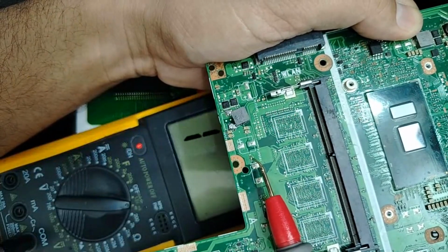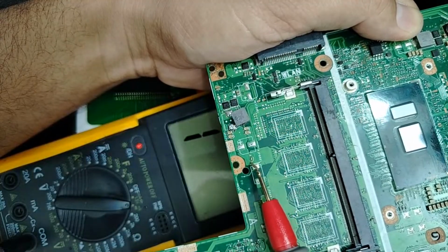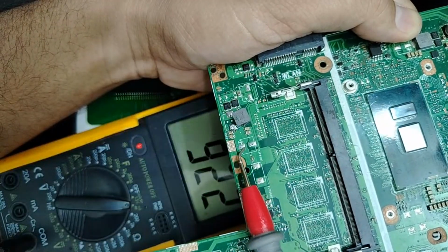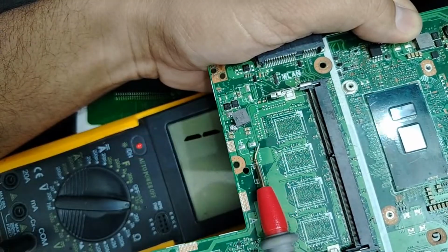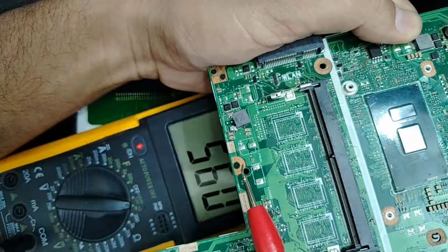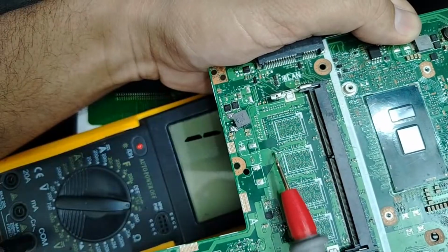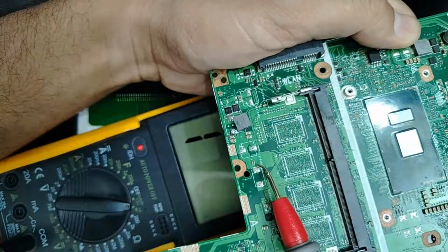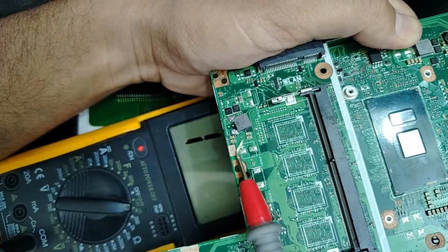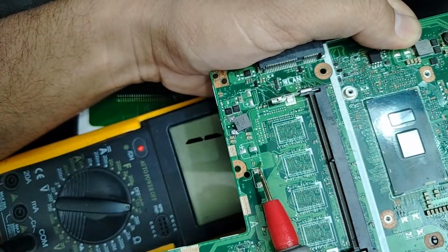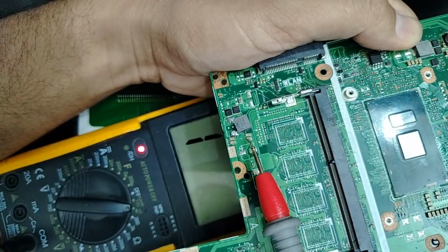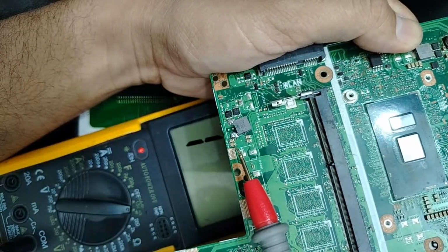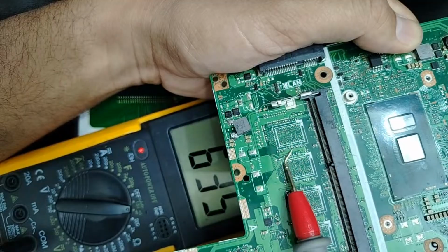We have this guy here. Do you see this one? If we remove this one, we will separate this side where we have the ceramic capacitors from this side, the motherboard, because here, my friend, this point means the motherboard goes. The voltage here is connected to all the motherboard. If we remove this one, we will separate these two stages. It means if we find the short here, the short will be in these 4 ceramic capacitors. If we remove this one and we find the short gone, not here, it means it is on this side.